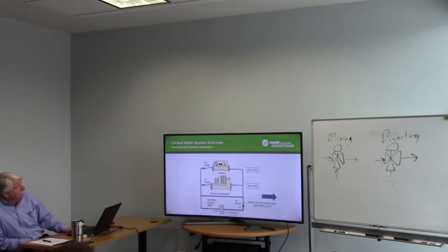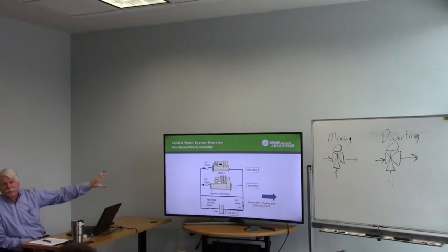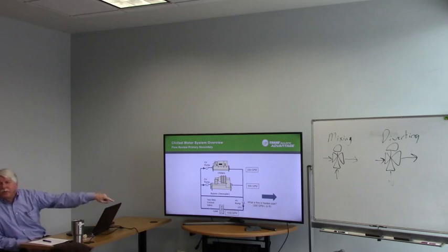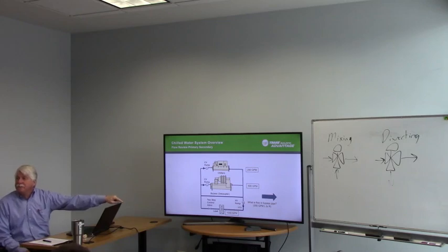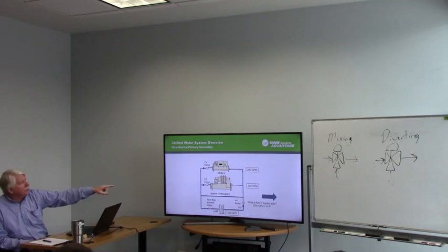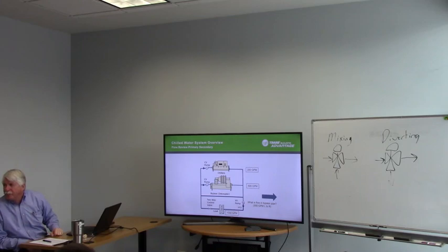Now, this was the way centrifugal plants were built 40 years ago. Okay? And the reason is that down at the bottom there, you see we've got two-way valves and VFDs. So we're saving energy there, right? I mean, we're only using as much water as we need, and that's called the distribution loop. But up in the top part, we're still running both those pumps at design GPM all the time. And that's wasting energy.